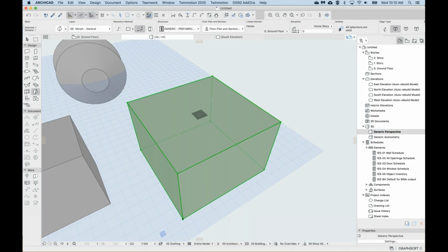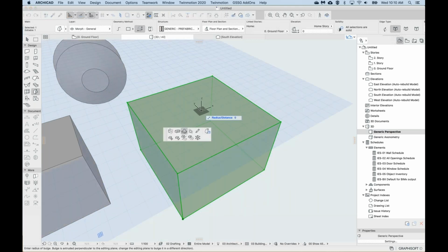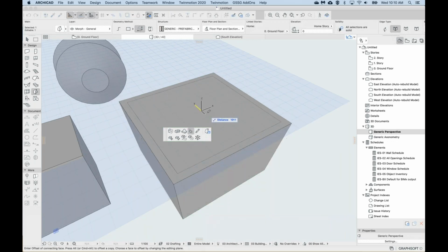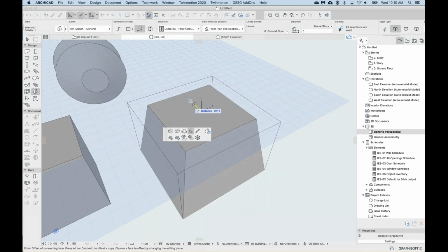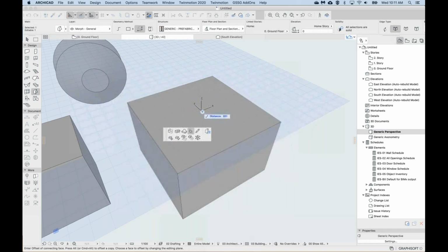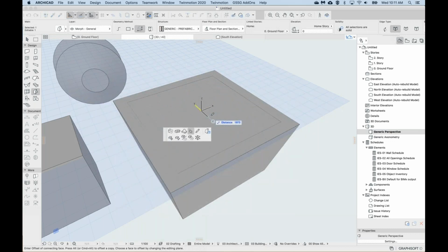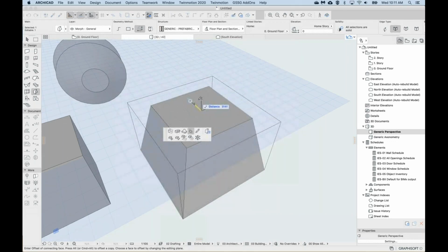Okay, so I'll show you now. What I'm going to do is click on the top surface, like what we did before with the push, pull, tube, and bulge. And now I'm going to choose the offset all edges option. This gets a little bit complex. I'm going to offset all edges, and if I move my cursor, you can see it's offsetting all of the edges. This is similar to the offset all edges for a slab or other polygon tools, or fill, for example.